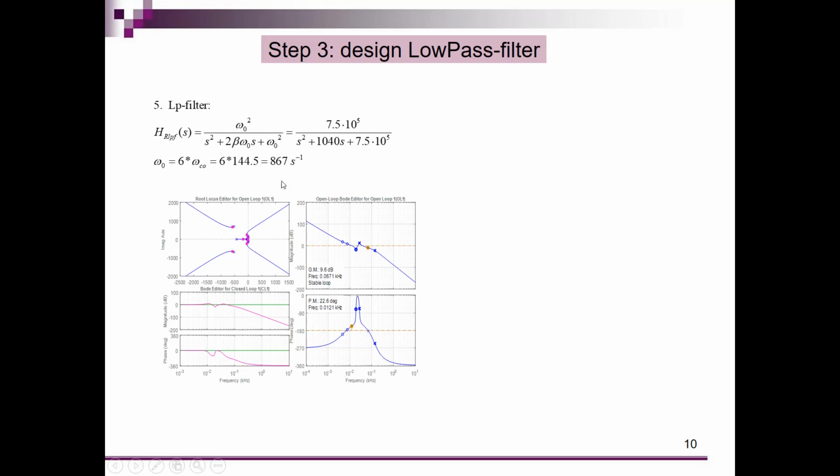And when you do that, this is my open loop response again. You see that the phase margin somewhat lowered over here. So again, low pass filtering also yields a somewhat lower stability, which we see by that phase margin. And what you also see is, because we have a second order filter over here, I have a maximum phase drop of minus 360 degrees over here.